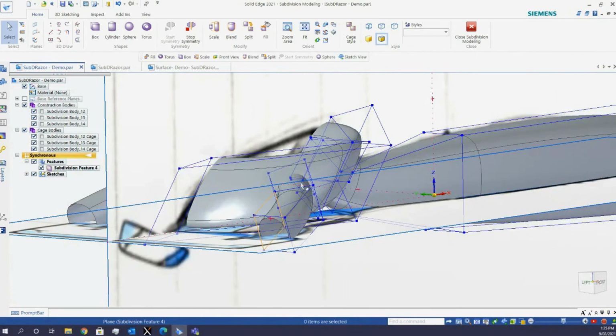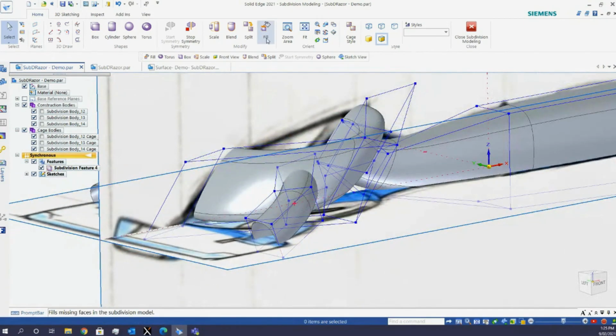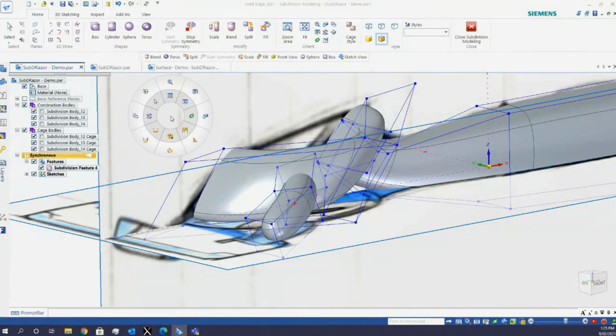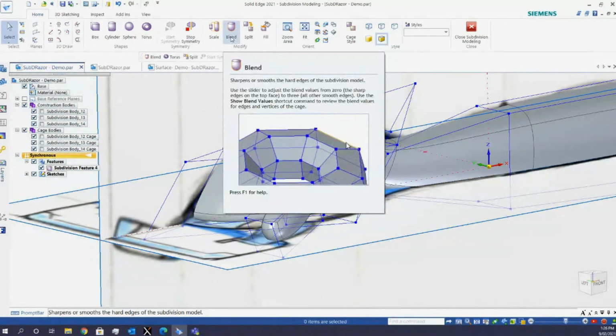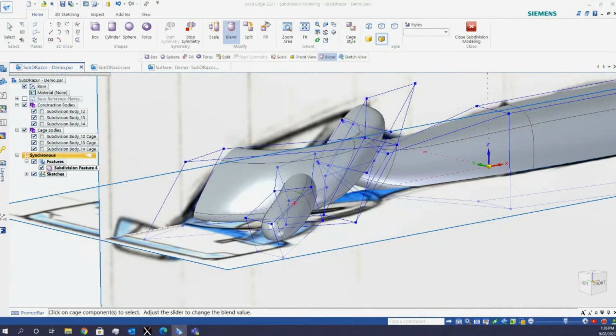Now I'm going to close this area off by using the fill tool, selecting fill. You're not working with the geometry, you work with the segments. You just select the edges and you can see that it is closing it off. Yep, I want it to be closed. I do that to the next one as well. So both are closed. If you're not happy with the end result, with the ends, you can always use the blend tool to control your closed area or your ends.